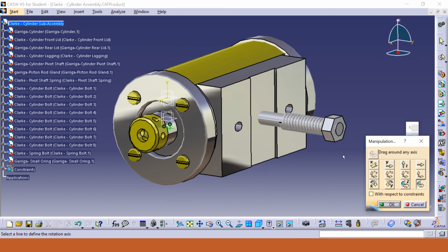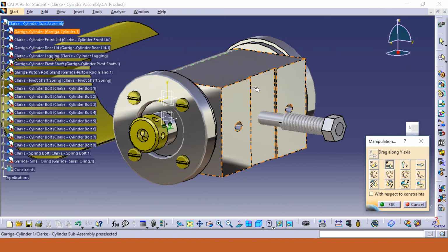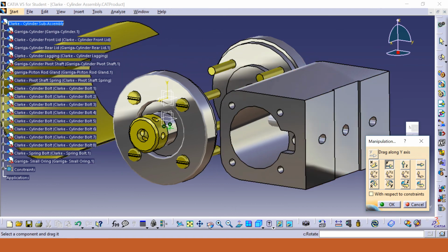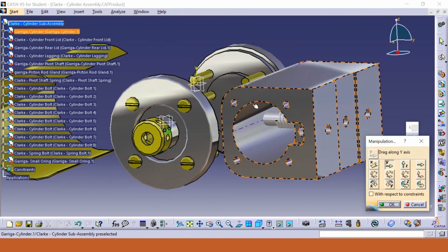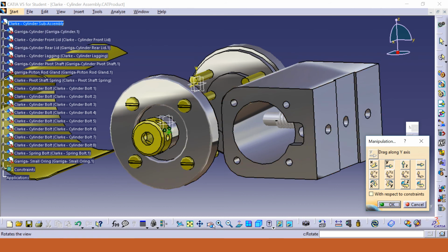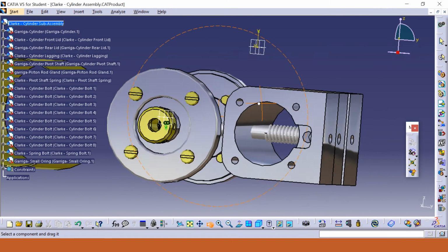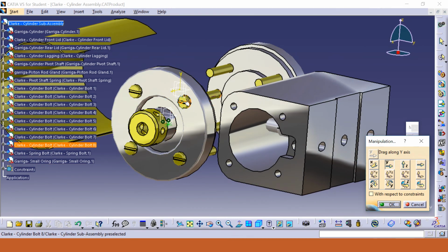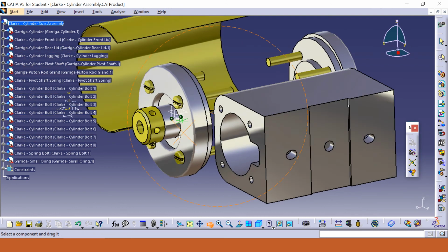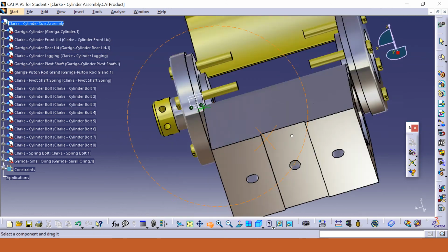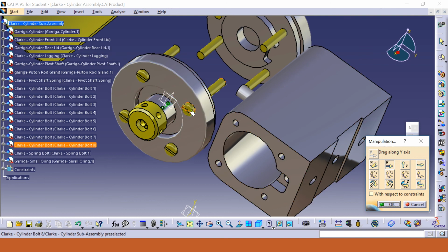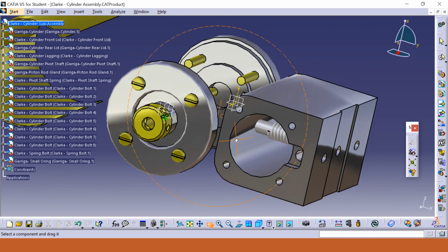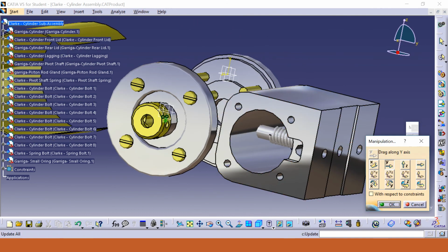As stated before, the cylinder is made out of hardened aluminum and steel. It is a much stronger material than the other parts. The reason for this is because when you remove the lagging, which is this portion up here, and you remove the cylinder, this is where the piston assembly moves in and out. Because this portion is subjected to a lot of stress, 8 bolts were used in total. These holes are threaded, and they fit these bolts right here. When the rear portion, which is this, and the front portion are put into place and the bolts inserted into each of these holes, the cylinder assembly becomes very strong and able to withstand the pressure exerted by the pistons.